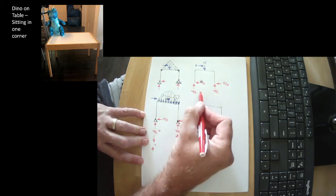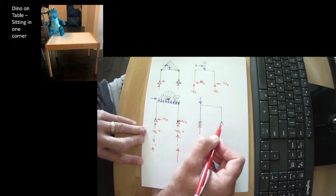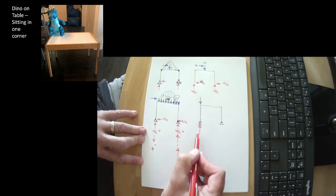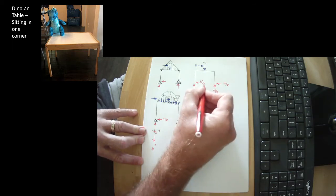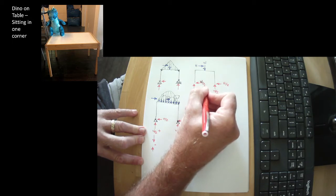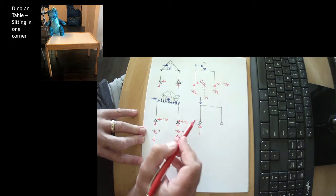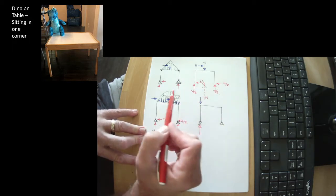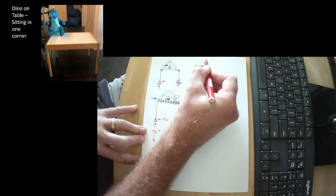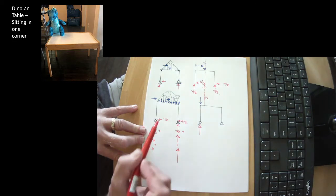And so for equilibrium, 100% of his load, this is actually something quite interesting, that the resultant of the load has to pass through the applied load. So in this case, up here, I'm going to dash in the resultant. The resultant is the sum of all the reactions applied at the centroid of the reactions, and the resultant has to line up with the applied load.